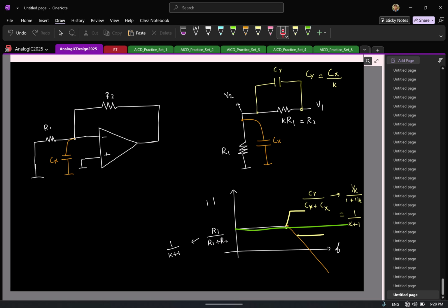So this way you can go and add a capacitance, and if you choose it to be the sweet spot value, then this basically behaves like your old feedback network, where you just had only resistors. So that is one quick patchwork you can do to basically tackle the input parasitic capacitor.